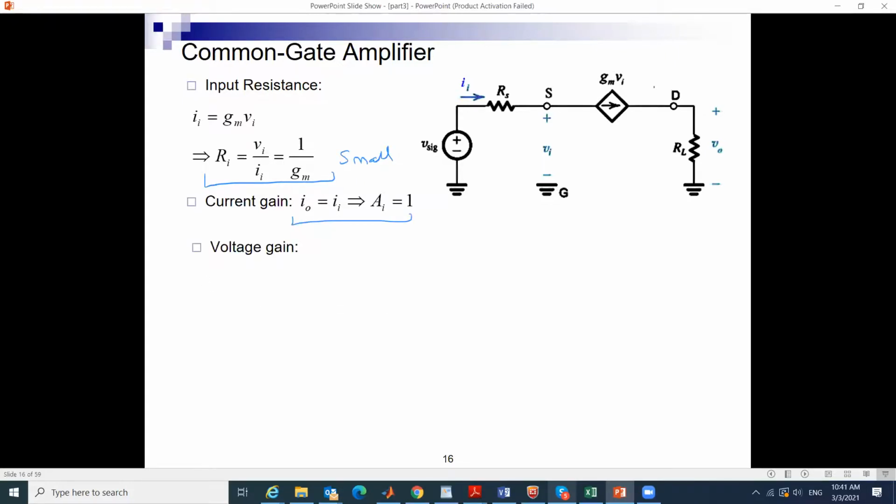And what is the voltage gain? How do I derive the voltage gain? Here Iin is continuing here. So Vo is RL times Iin. And Vn, I know what it is. So I can find the gain. So let us see what is Vn. What is Vn in terms of Iin? It is Iin times Rn, which I already computed, right?